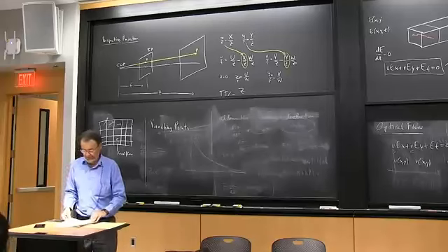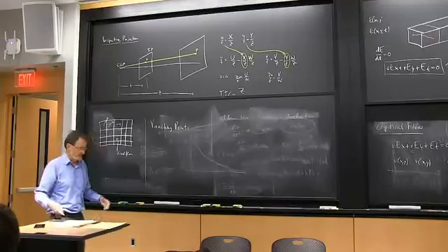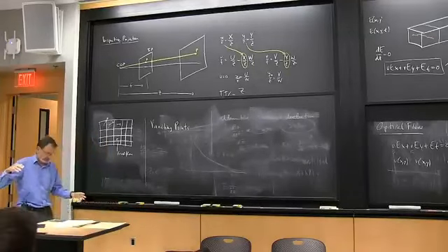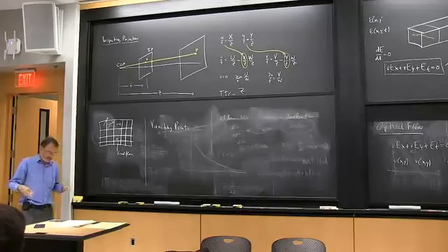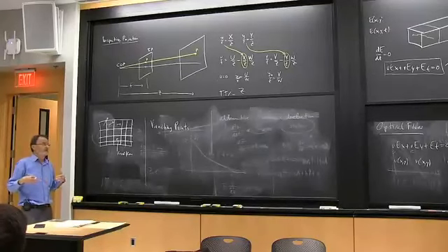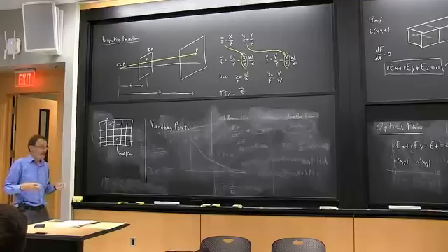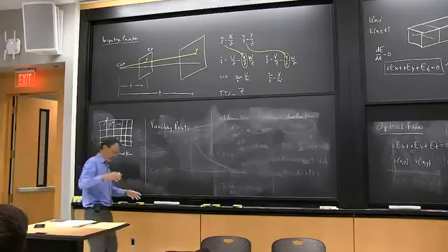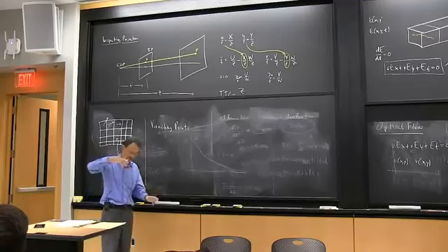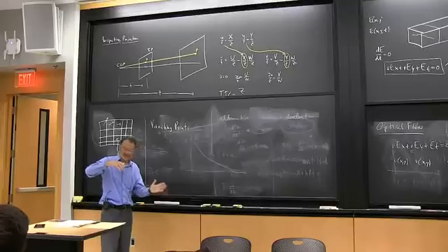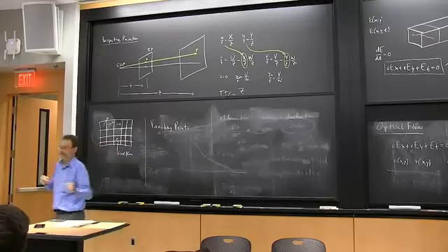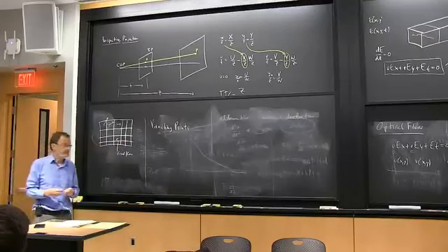We can actually exploit that. If, for example, you're hovering above some building that, like the main buildings at MIT, is all on a rectangular grid, you can determine from the image certain vanishing points, and from that you can determine your rotation relative to the coordinate system of that rectangular block.